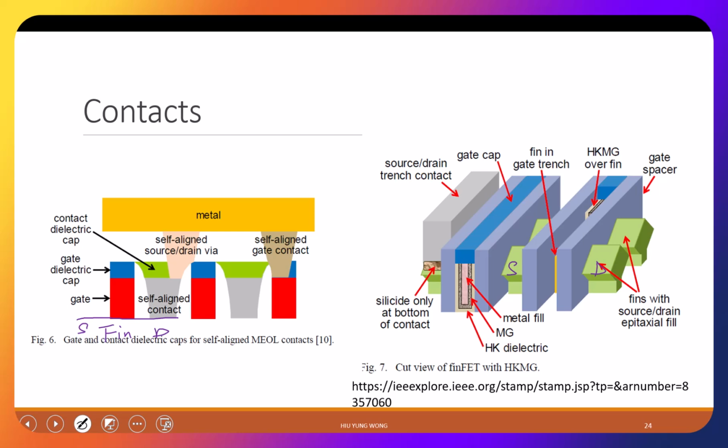No, this is the gate oxide. So imagine I have the fin here, right? This is removing everything. This is the fin. Do you just see this yellow one? This is the fin moving from left to right. So in this part, I need to wrap it around with the gate, right? So the first thing I will wrap around is the high K dielectric.